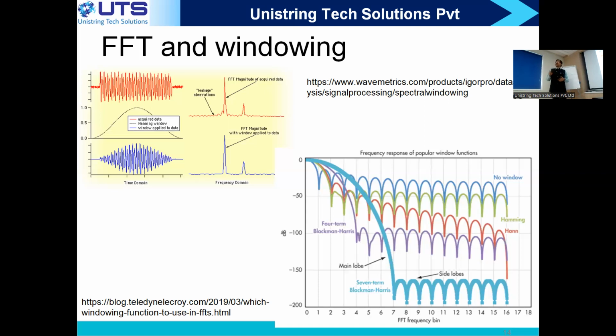I think you have a lab session this afternoon where you are given a pulse Doppler model, a MATLAB model, Octave or MATLAB, any software you can use to run. You change its window function. Now you will see in the range Doppler map that even though the energy is at one fixed range and one fixed Doppler, you don't see only one peak. You will see a spread. Okay, can you go to the next slide?